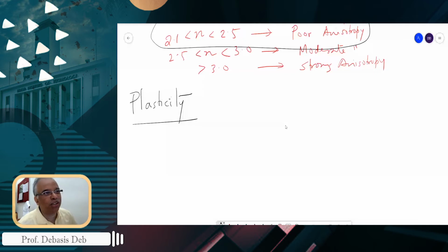So this plastic bottle, do they have E and mu? If I test, will they have modulus of elasticity and Poisson's ratio? Yes, they will. So they are also elastic, that means. Because those are elastic properties, up to a certain limit. So always remember that every material is an elastic material until a certain load, a certain stress.